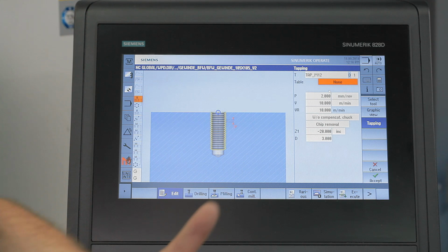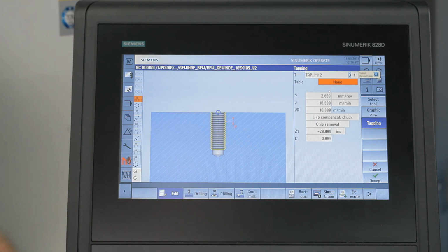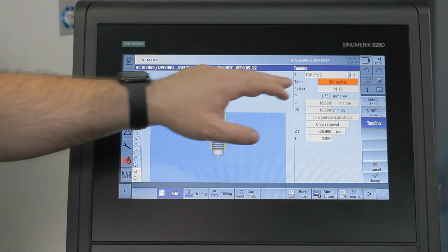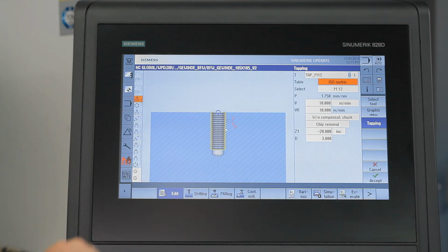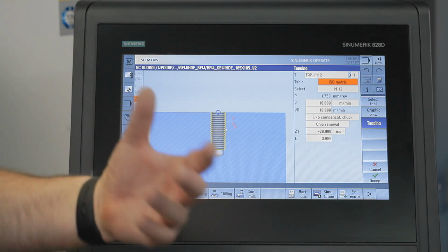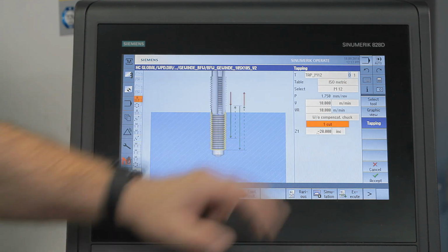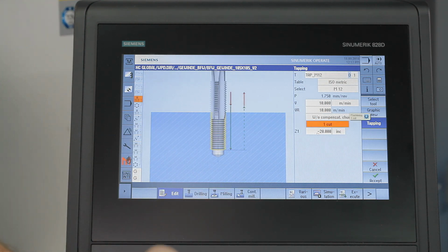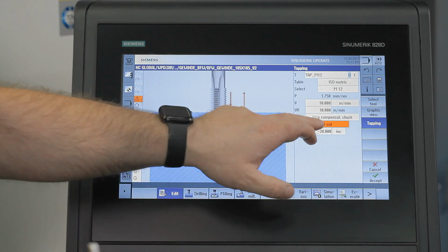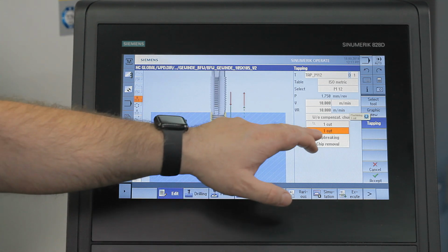Of course, it's also possible to work without the thread table. In this case, however, all values must be entered manually. The tabular selection enables fixed presetting of the pitch, thus allowing us to cut the thread using different technologies. So what do we mean by different technologies? Either in a single step through the hole, in and out in one stroke to complete the thread in its entirety, or to avoid any chip congestion by applying what's known as the chip breaking method.